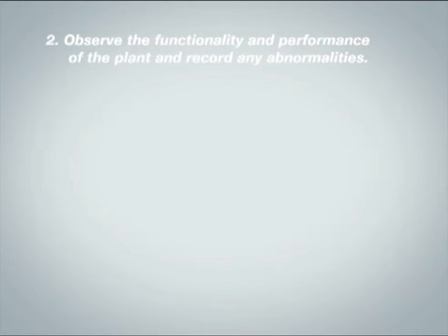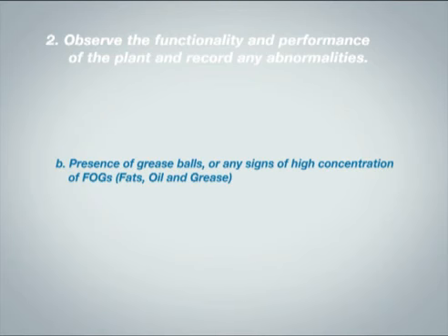Observe and record the following. A. Color and concentration of the influent wastewater. B. Presence of grease balls or any signs of high concentrations of FOGs, fats, oil, and grease. C. Setting of the EQ discharge valves.